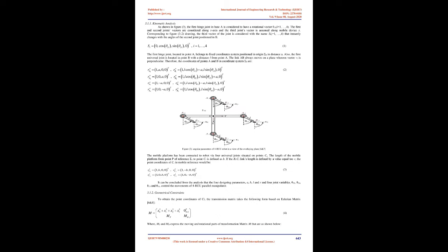In [10], the robot is divided into several parts based on operator torques, and each part is approximated with a fixed curvature. In cases that large forces are not imposed onto the body of the continuous robots, the approximation features a good precision. The method has been repeatedly used for the estimation of the kinematics of continuous robots in the absence of external loads [11].